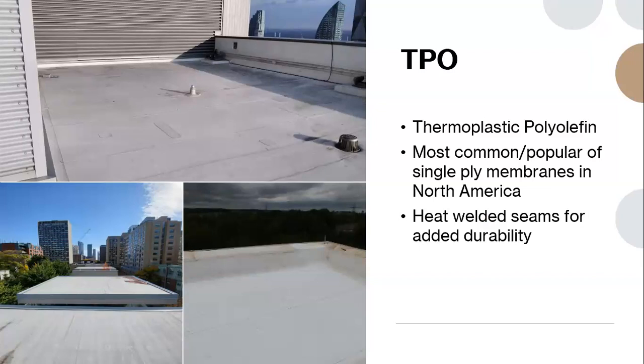I can definitely take that question, Andy. Sure. Birds tend to peck at the EPDM roof to get at the insulation, not necessarily for nesting, but they do for whatever reason like the insulation below. So it is a common problem that we find that happens with holes on EPDM roofs.